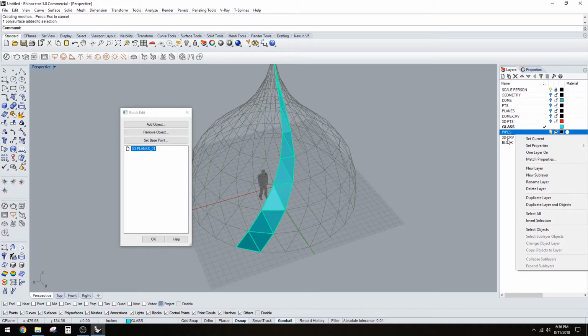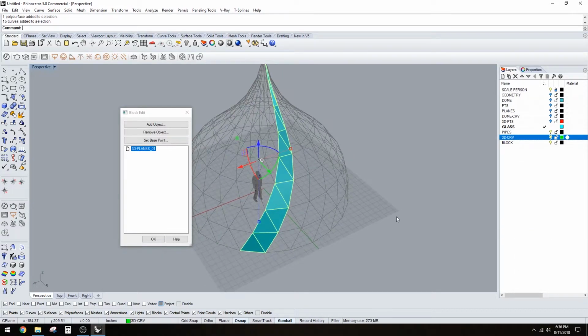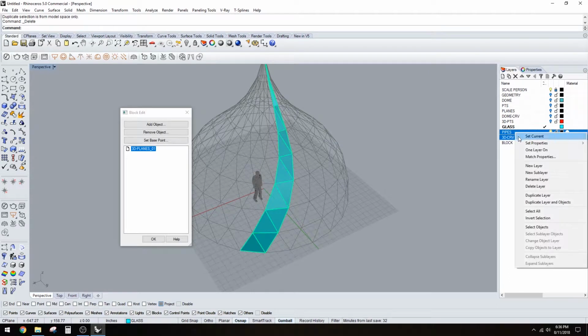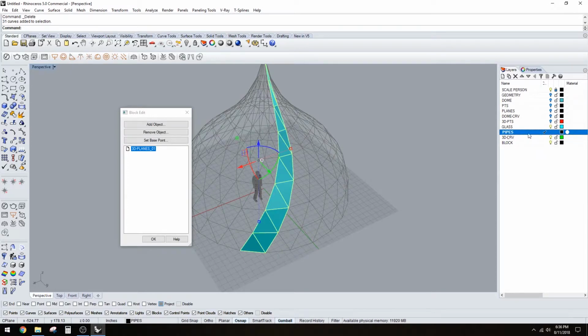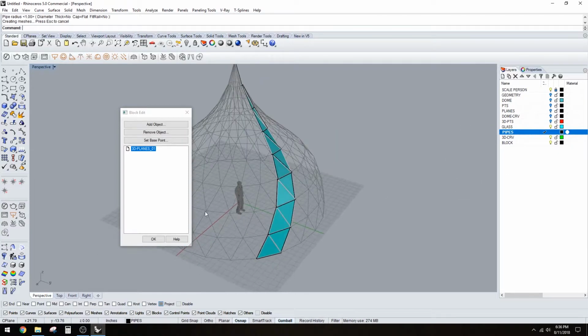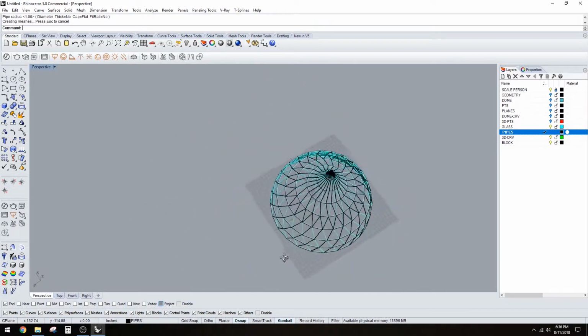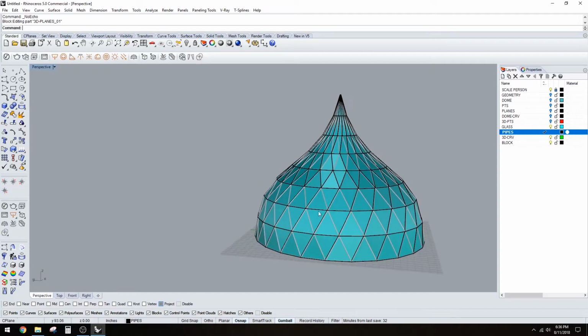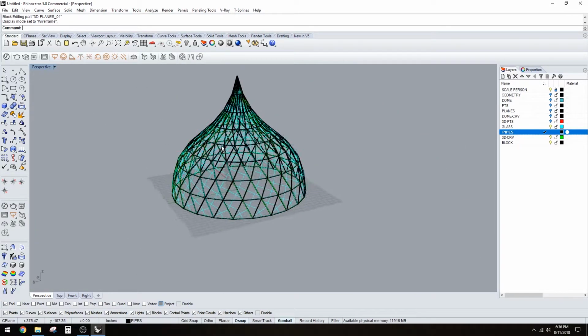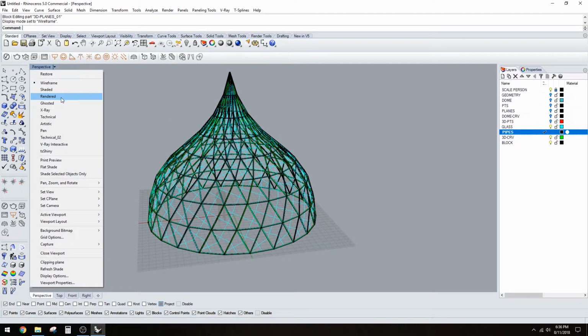And then we can go ahead and select the curves here. You can explode them, so there are single objects, and you can select the duplicates, which are going to be the ones in between. Those are going to be copied. And if you select those curves and make your layer pipes, and type in pipe, let's make it a radius of 1 inch. And so once you have that, you should have a completed design, which sometimes has a hard time refreshing. There we go, it's a pretty cool design. And if we go to wireframe, we'll see the person there. Let's go to ghosted.